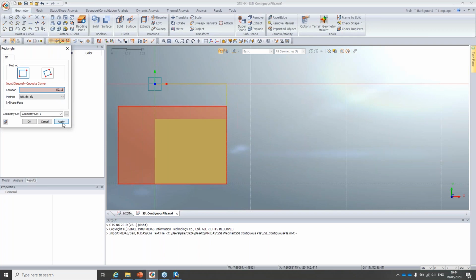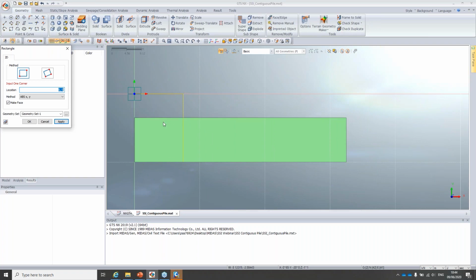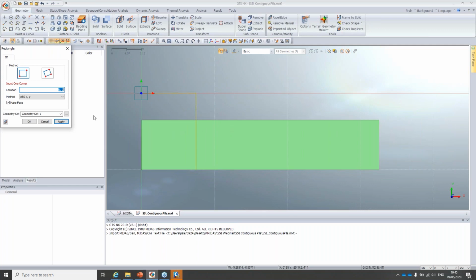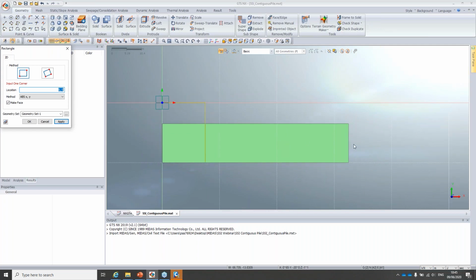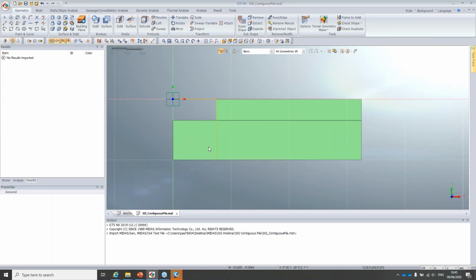length of this element. Basically, you want to make sure that this is wide enough so the results we're getting at this edge are not influenced by local effects of the structure. So we are making an assumption that 50 meters is enough. If on the results we are seeing that there's too many local effects here still, maybe we need to increase the width of this element. And we do the final one, from this point to this point. Okay, as I said, that's just the geometry.